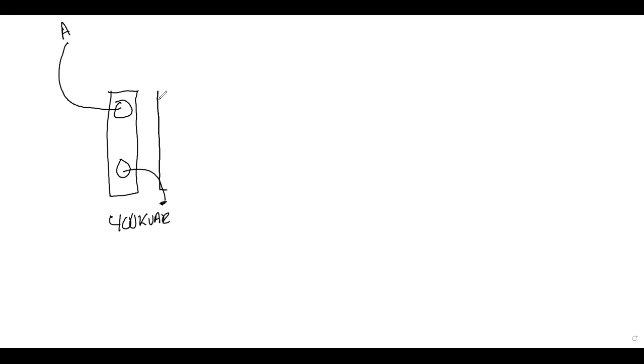Paralleling is putting another unit in the rack, in the hole right there, right with it. Now I'm going to ground this one and take this lead and go over to the next unit. That is paralleling the unit. All right, 400 times 2, now I have an 800 kVAR unit. And do understand, that is for that phase. If I do it on that phase, I've got to do it for B and C also. Good? Okay.